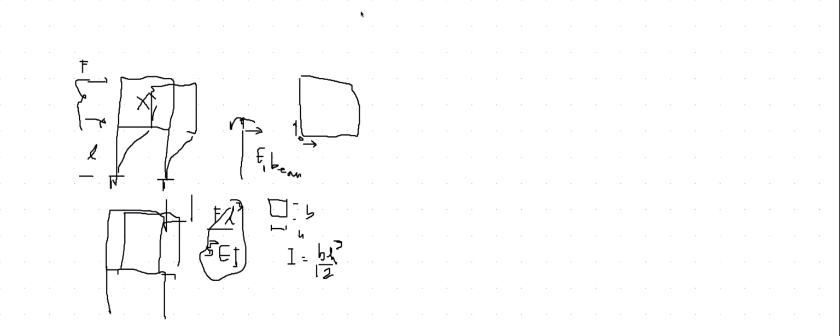And the behavior of the beam becomes like that because it remains built into this end. So it is not really the type of thing that you want to have here. It would be more like L to the power 3 divided by 12. So this result would be F L to the power 3 divided by 12 EI.